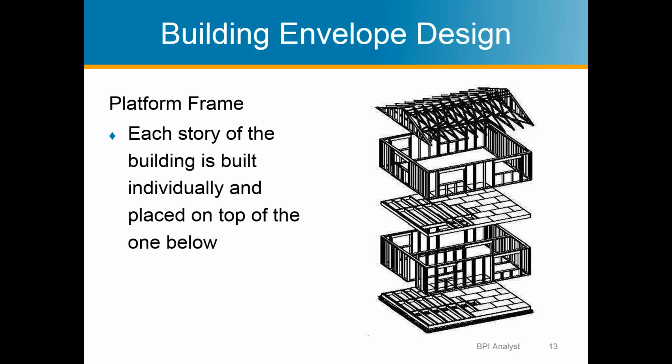There are other types of framing, of course. There's balloon framing, where a stud could go from the first floor to the top of the second floor. One stud goes all the way up. That's how houses used to be built. There are some building science issues with it, but we don't really see it anymore. It's going to be in older homes, probably pre-1950, pre-40 maybe. And then there's other types of framing that you just won't see much, but typically we're talking about platform framing.